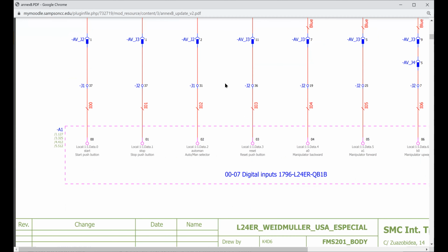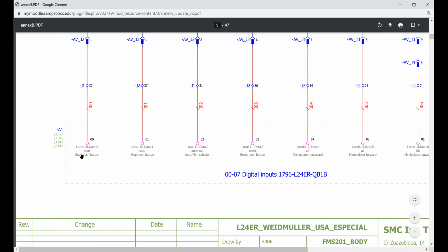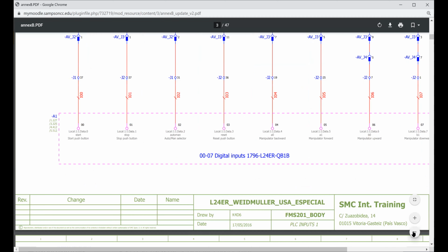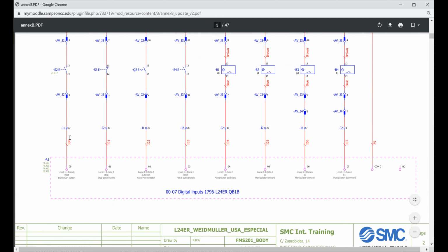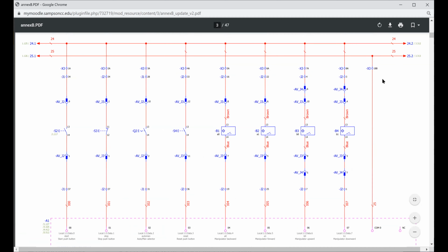And you'll also know how to check an input. You put the red probe on your meter on that terminal, and you have to find a common on that input section. The common would be a step back. The common's over here. So to check the input for the start button, you put the red probe on your meter here on J137, and then you put the common probe over here on that terminal, X3 18B.